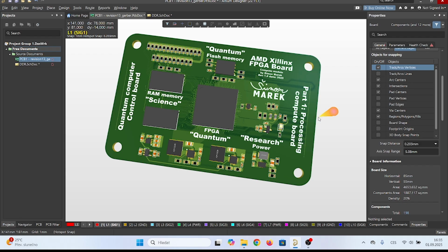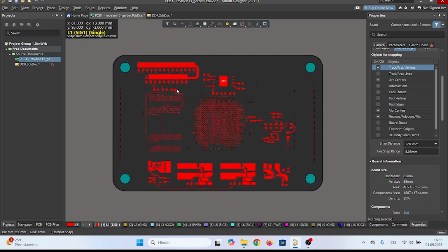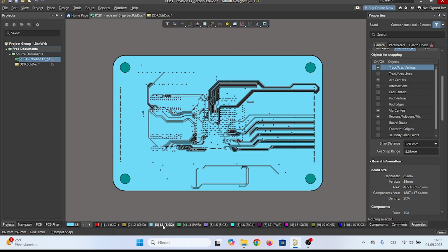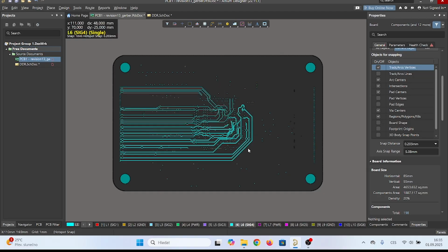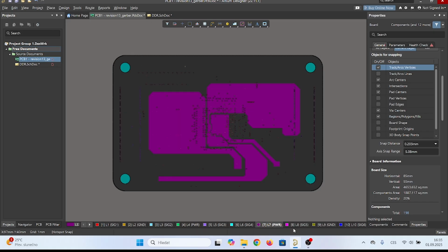So this is really how you place your components on your FPGA board. Typically on your top layer, you will connect the simple connections. Then you have other layers which you can either pour by ground or use for other connections. This is how you connect your connectors to the FPGA, and this is your power layer where you connect your power to the FPGA by placing big polygon pours. So this is very beneficial.